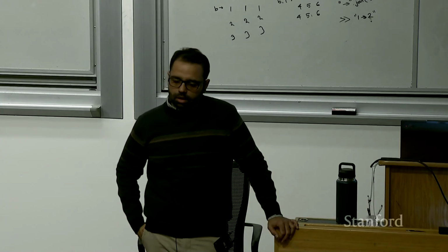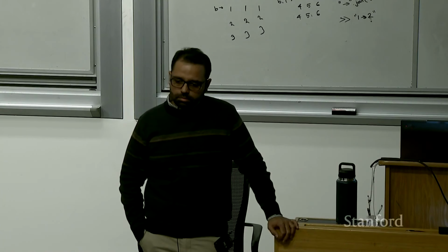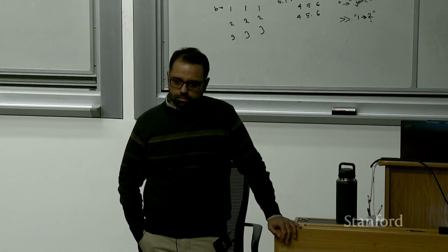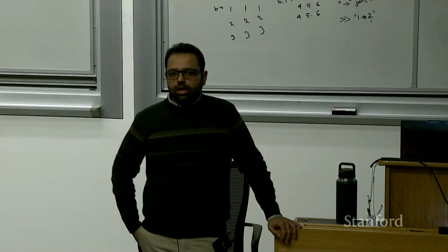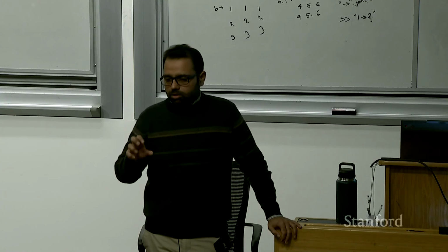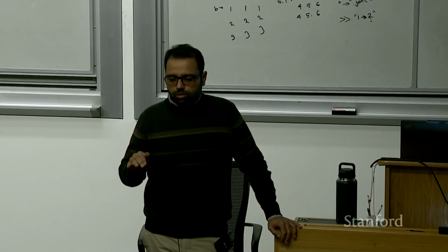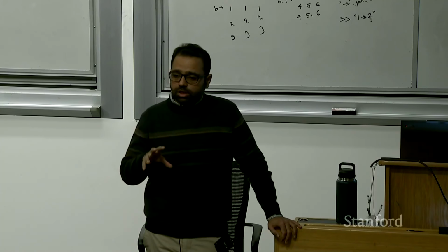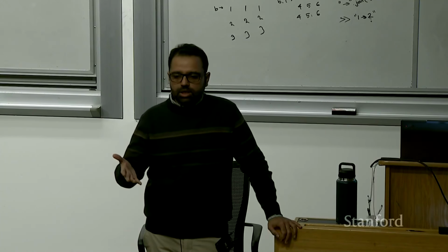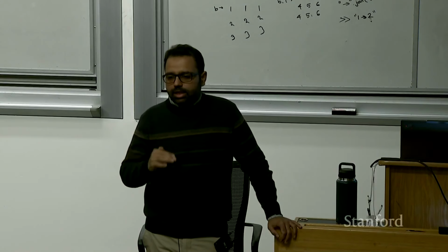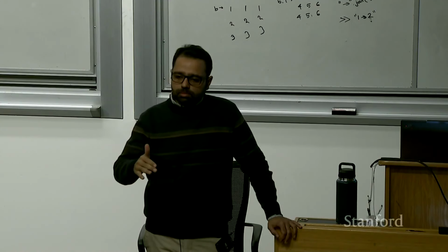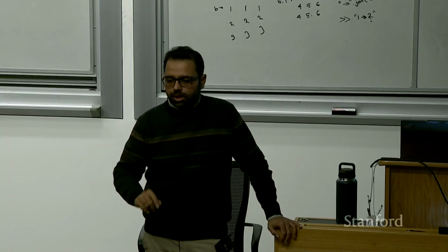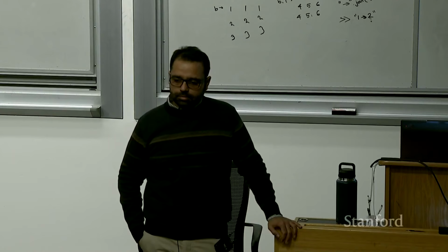I see. But after you finish your training successfully, then it's equally easy to sample a goal near an obstacle or far away from an obstacle? If you are following the gradients, because it's an approximation, it can go to local minima. But if you use this neural network as a value function and incorporate it within some MPPI, then it helps overcome those local minima issues, and it does well. I see. Yeah, cool. Thank you.